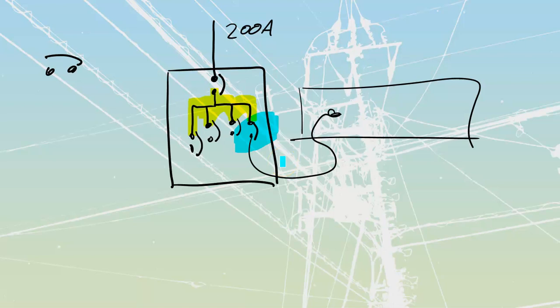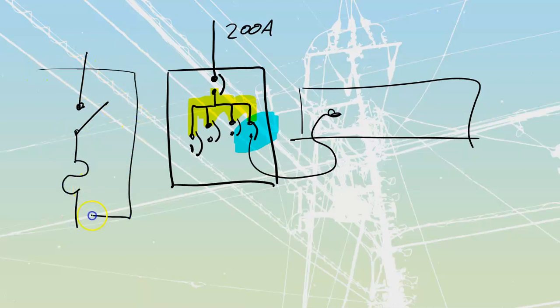Fusible disconnects are sometimes used instead of combination panel boards, where we're going to come into a service and go through that fusible disconnect. It comes in, enters into a set of lugs, we have that switch, and then we have that actual fuse section. This is all going to be inside of one main assembly.